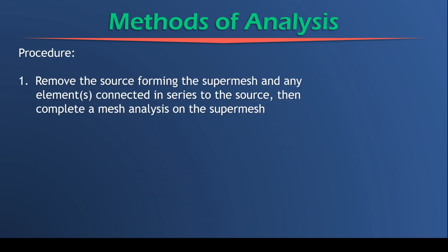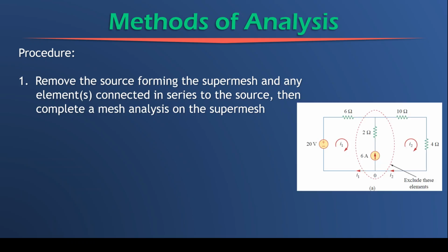What is the procedure to solve circuits that have supermeshes? So first, remove the source forming the supermesh and any element connected in series to that source. Then complete a mesh analysis on the supermesh.